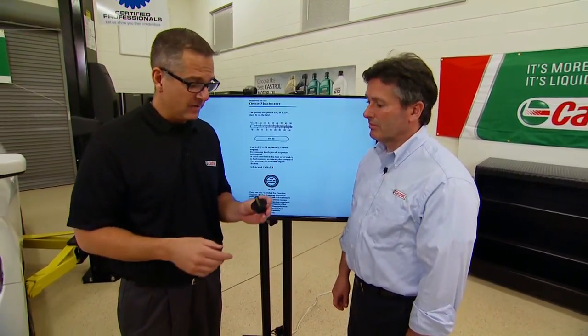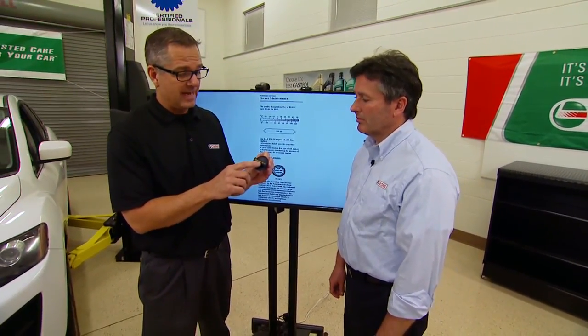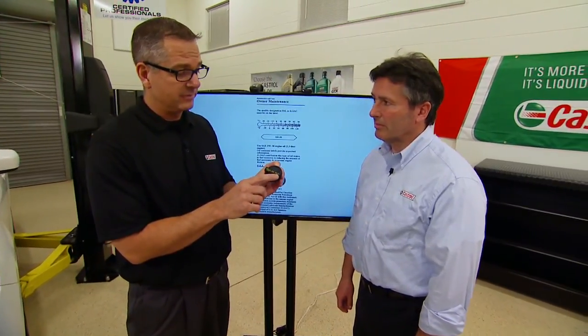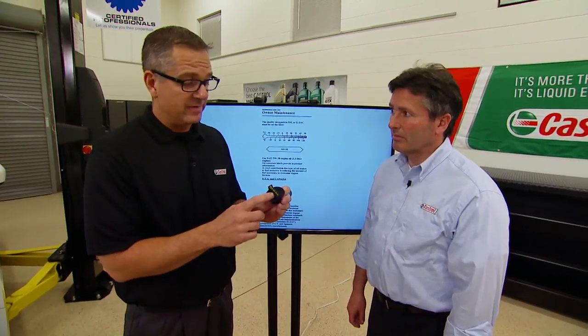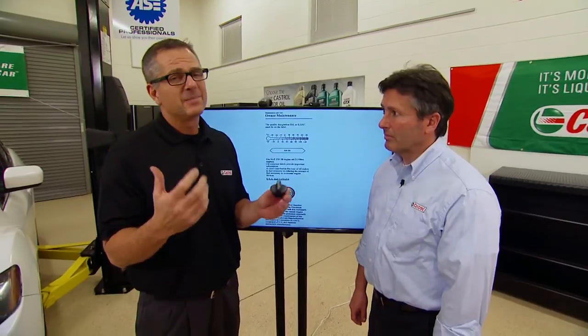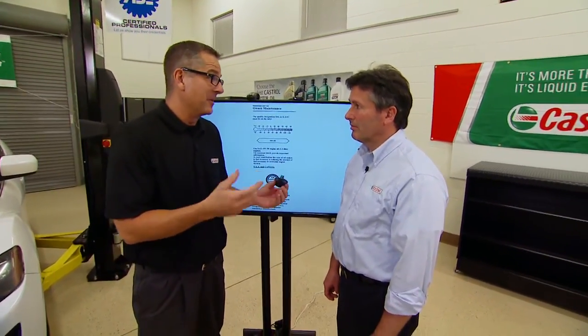First of all, I just pulled a cap off, and right on the cap it says it's an SAE 5W20. That cap comes from the vehicle, that's the oil that goes in it. You might still want to check the owner's manual. It could be the wrong cap.